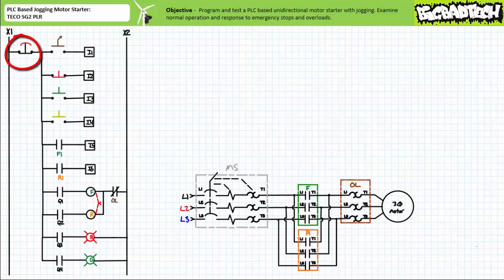Note the maintain contact normally closed e-stop is not a direct input to the PLC, but rather serves as a hardwired bottleneck through which all 6 field input devices immediately downstream of it must negotiate to issue input to the PLC. Wired in this fashion, the hardwired e-stop effectively severs all incoming communication with the outside world without the necessity of resorting to any programmed instructions to do so.